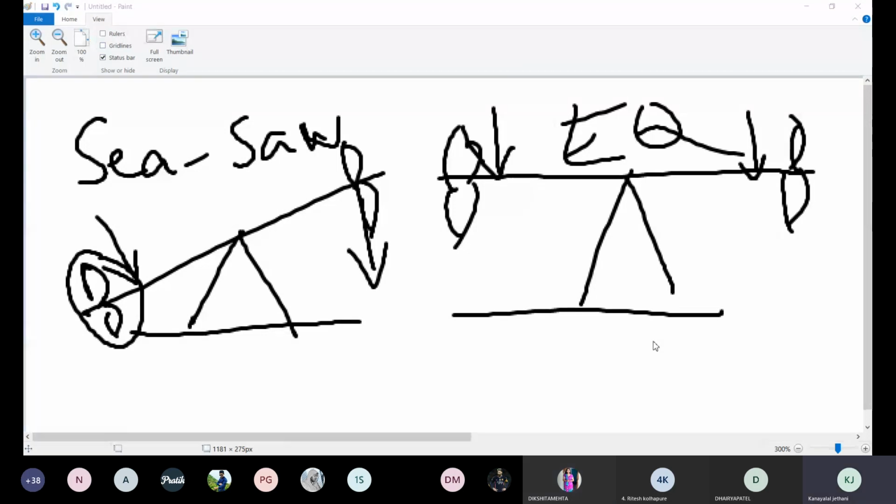That's what I mean. When there is no net transfer, that means there is no effect. You can't see the effect, right? What is happening, that is the mechanism. What you see is no effect. You don't see any change in vapor composition. You don't see any change in liquid composition. If there is net transfer, the composition of the vapor will change, right? But since there is no net transfer, there is no change in the composition of the vapor. Although whatever the underlying mechanism is, it may be there. Some liquid goes to vapor, some vapor comes to liquid, but net transfer is zero, right?